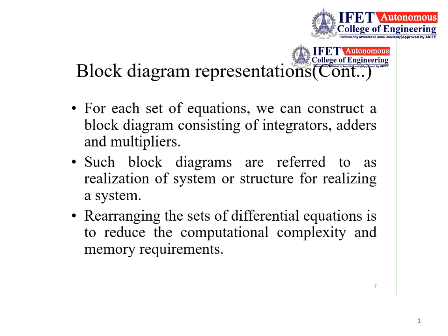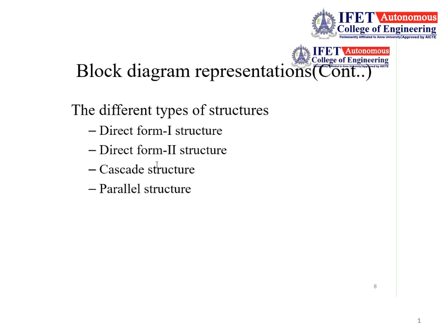We can rearrange the set of differential equations to reduce computational complexity and memory requirements, because in block diagram representation we have different types of structures: direct form 1, direct form 2, cascade and parallel structures. Many other structures also exist, but here we are going to discuss only direct form 1 and direct form 2 structures.